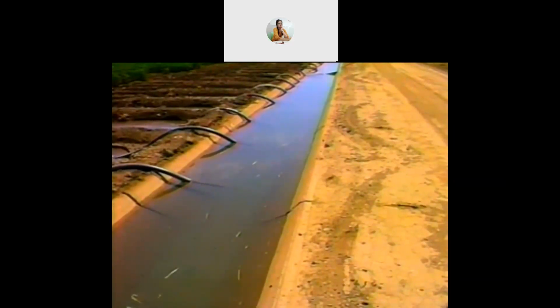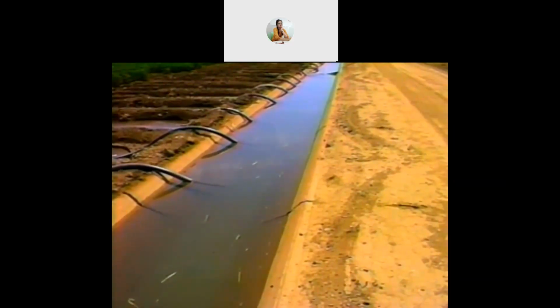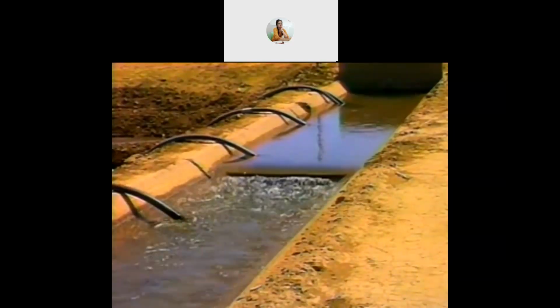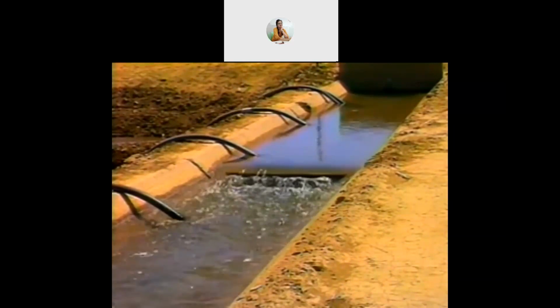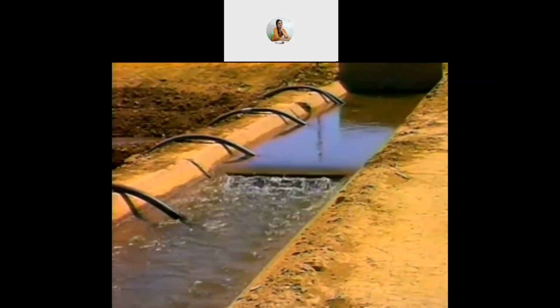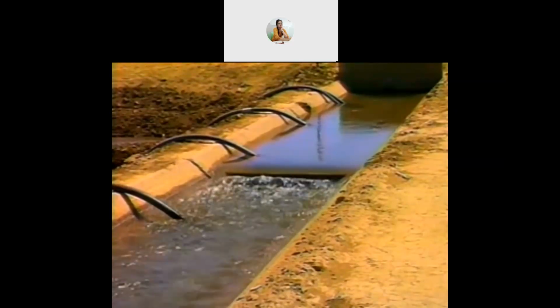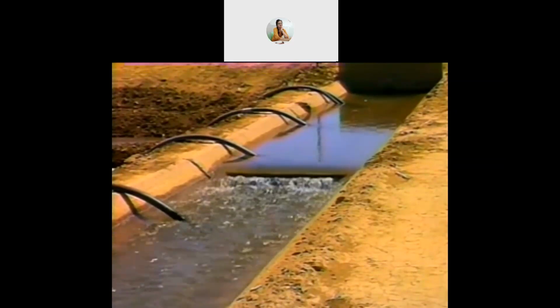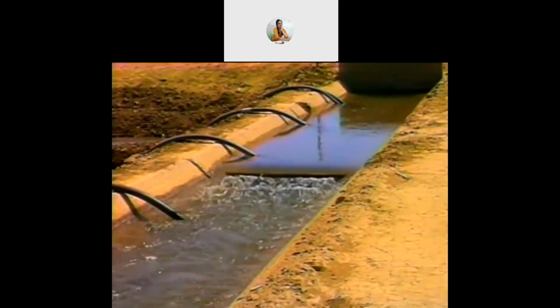Flow rate is the amount of water that is flowing in a ditch or furrow in some amount of time. For an irrigation canal or ditch, flow rate is usually measured in cubic feet per second, but may be referred to as CFS, feet, or feet of head. In some districts, the flow rate in the irrigation canal is given in miners' inches, or inches.